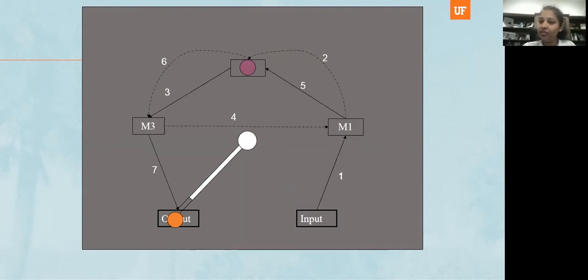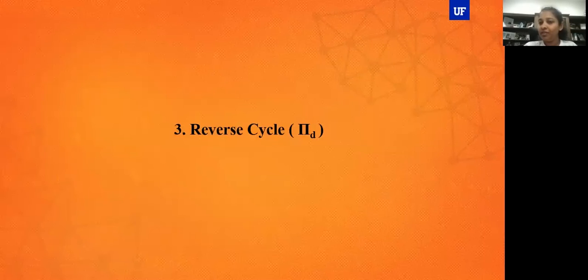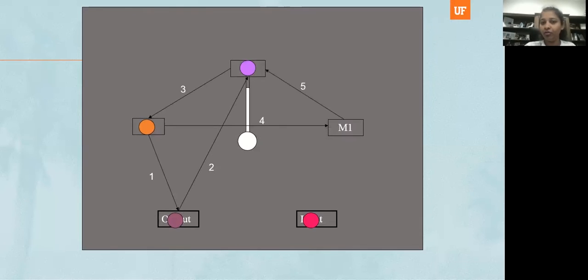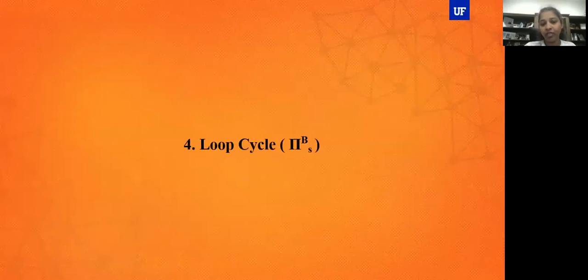This is why it is called the odd even cycle. So the robot first goes and loads the odd machines, then it comes back and loads the even machines. The third one is the reverse cycle. It simply says load in the reverse sequence. So here is the steady state cell. You keep on loading in the reverse order. First you unload, then you load machine 3, then 2, then 1. Then the cell comes back to the initial configuration.